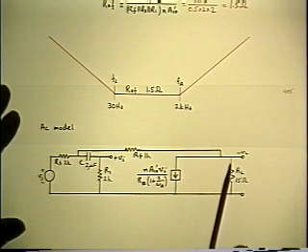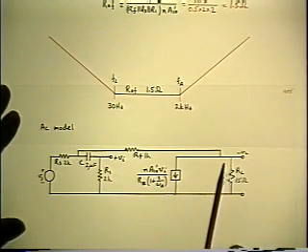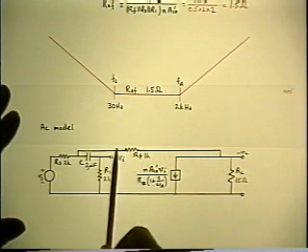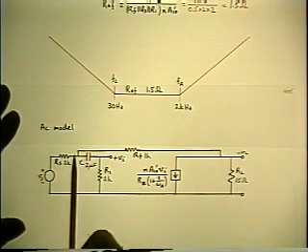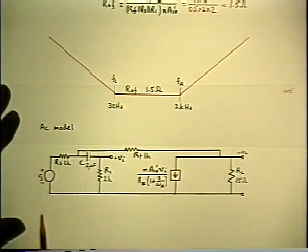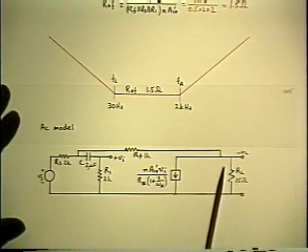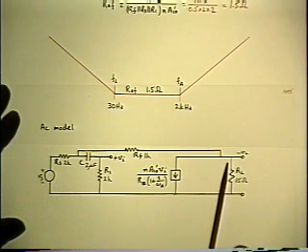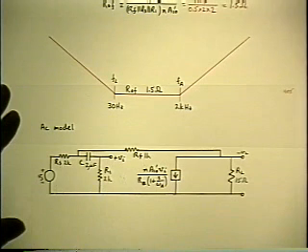So the only contribution to the 0 frequency output impedance is the impedance of the feedback path itself plus Rs, the capacitor being open. So the 0 frequency asymptote of the output impedance ought to be RF plus Rs, or 3K.